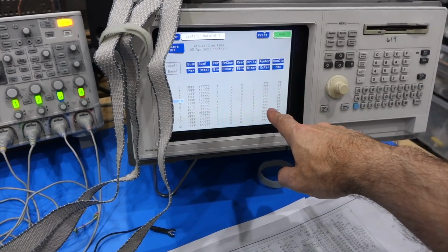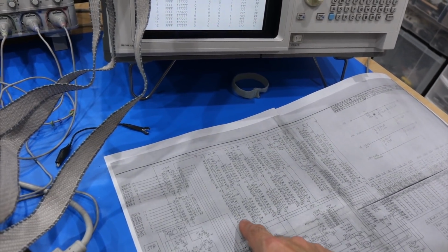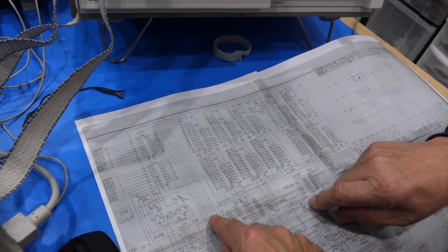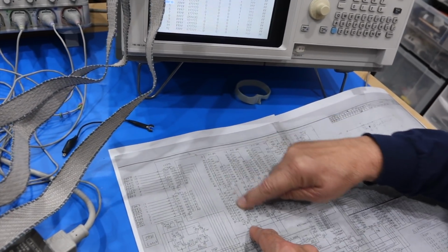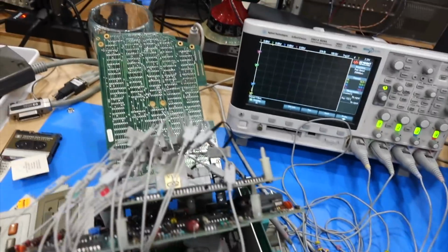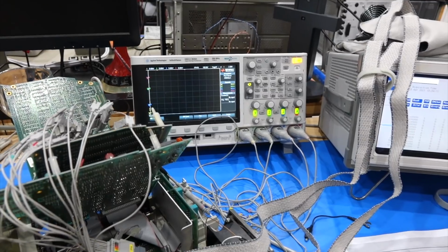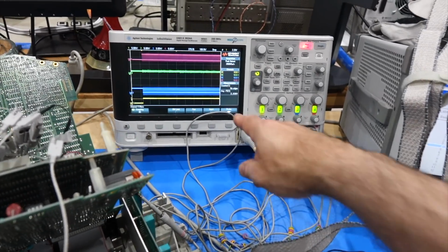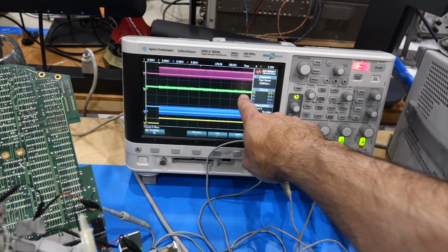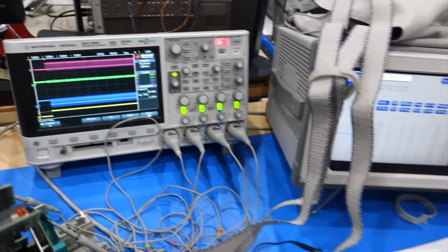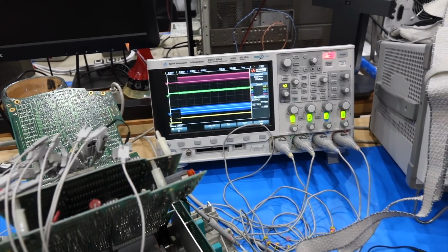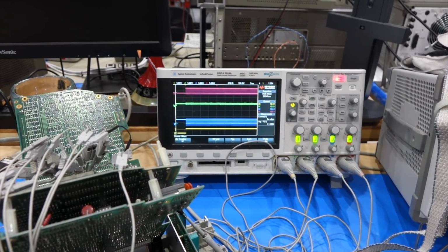So we see garbage addresses on the ROM, and we're wondering if the address doesn't get to the ROM at all. And the latch should trigger on the signal called STM prime, which also selects the ROMs to read. So which is also the second select to the ROM. So I have added a probe in green over here. If I trigger it, and yeah, I'm on 5 volt, and on STM prime, there is no latching signal. And that should have been high, except for when it's going low to select the signal, and it's not a valid TTL level. Well, no STM prime, and as we have just seen in the animation, this signal drives pretty much everything. So we have sure uncovered a fault, or so we think.